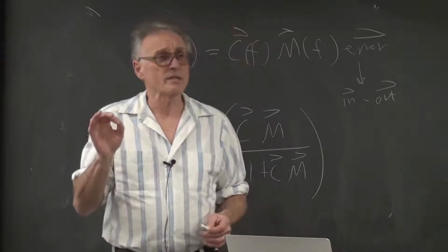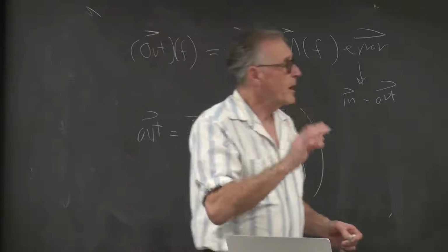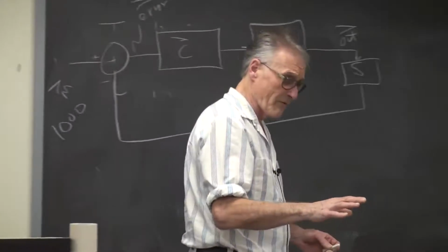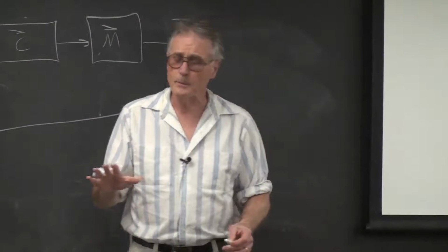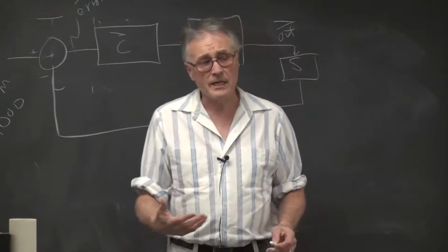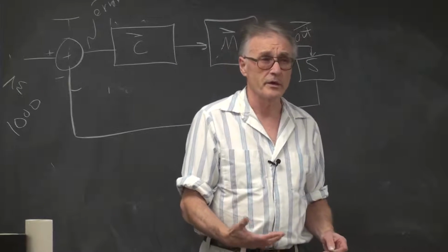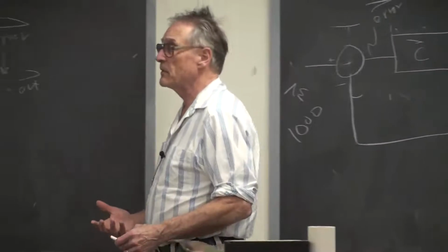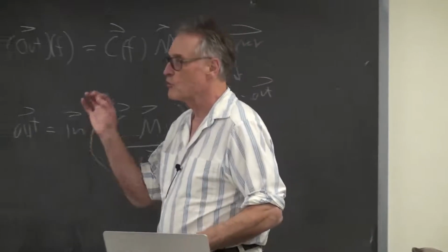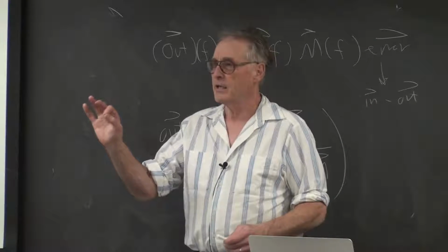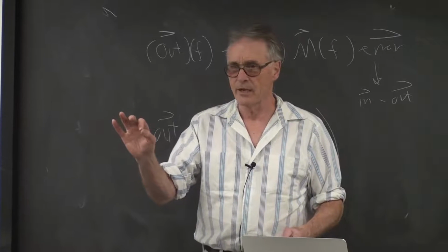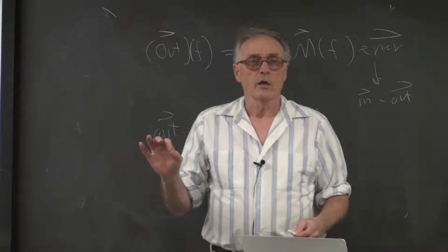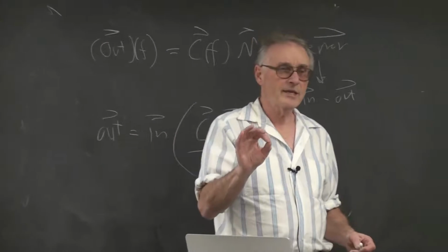It's actually a little worse than I've said, because while the formal gain of the motor, the phase shift of the motor at high frequency is 180 degrees, there's actually a little more phase shift that your circuit is going to inject. And that is, you only know the position or the speed at the last time a blade crossed the infrared. And until the next blade crosses the infrared, you have no information about the speed. Therefore, you effectively have an extra phase delay.